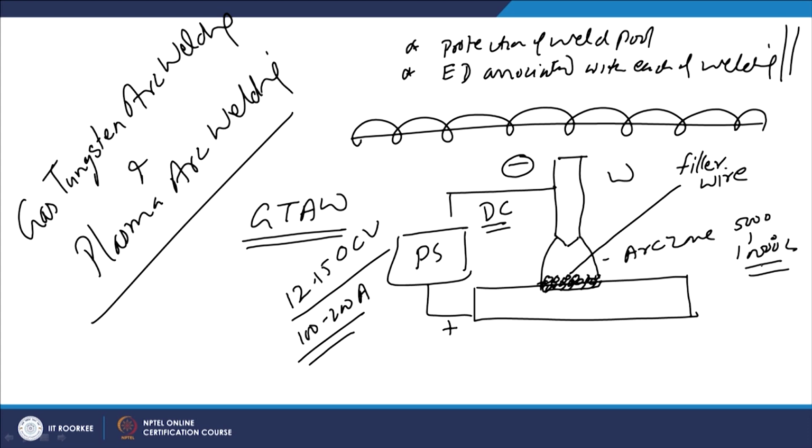The high temperature and enough heat generation through the VI facilitates the melting of the filler wire, which is the material to be deposited in the form of a bead on plate weld onto the substrate for surface modification. This material can be selected as per our requirement. It may be austenitic stainless steel for corrosion resistance, or it may be a nickel or tungsten carbide kind of material for surface modification as per our need. The idea here is that the filler metal is melted and mixed with the molten substrate, so that the required surface modification can be achieved.